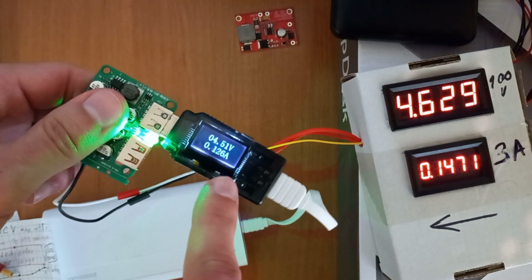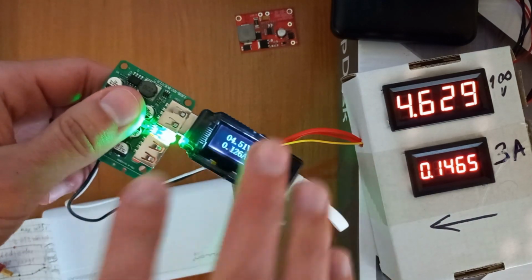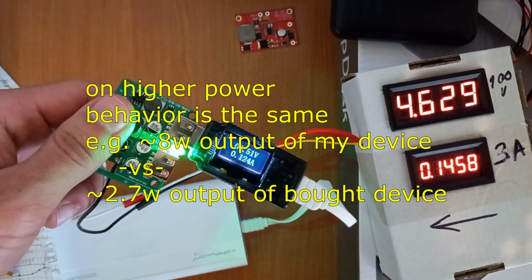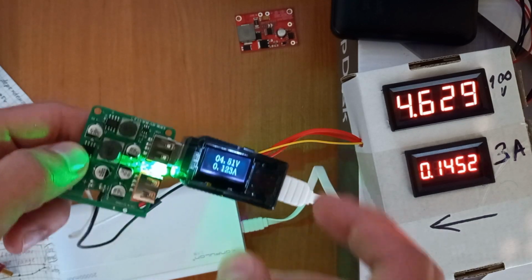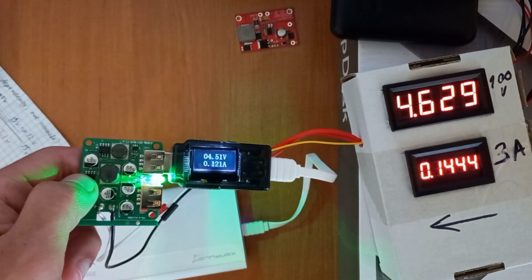You have 120 milliamps and the input dropped to 4.6 volts, roughly like the output. So it just drops voltage. It's a simple buck converter. It doesn't have any tracking. And further is even worse.